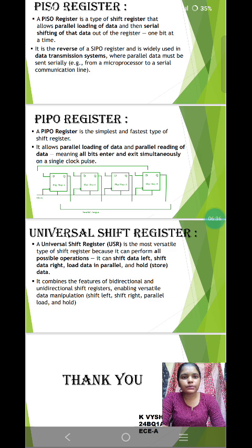How resistors are used. Current limiting prevents excessive current from damaging other components. Voltage division splits a larger voltage into smaller desired voltages. Setting time constants: resistors are used with capacitors to determine the charging or discharging time of a circuit. Setting circuit gains: resistors can be used to set the gain of an amplifier circuit. Signal filtering: in AC circuits, resistors are used to filter signals.